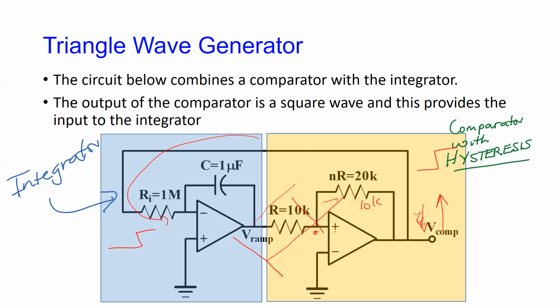And as soon as it passes through, remember, here's at 0, as soon as it passes through 0 going this way, this is going to drop. So this is now a step going this way. That is fed back through here. A step going this way integrates, it inverts, so the output starts to go back up again.